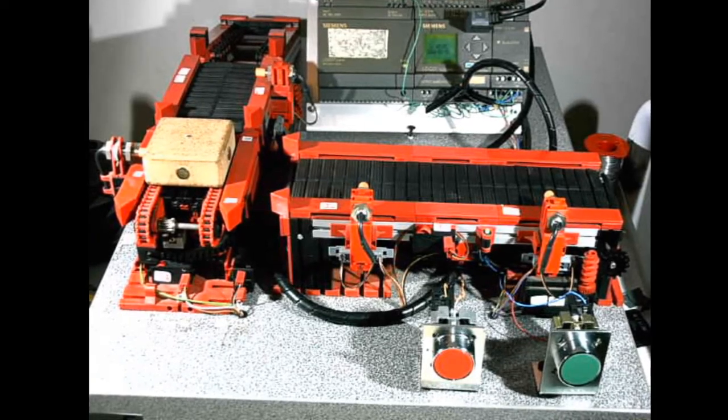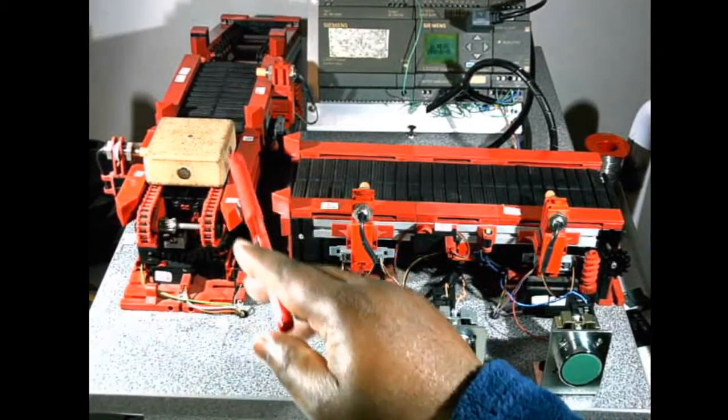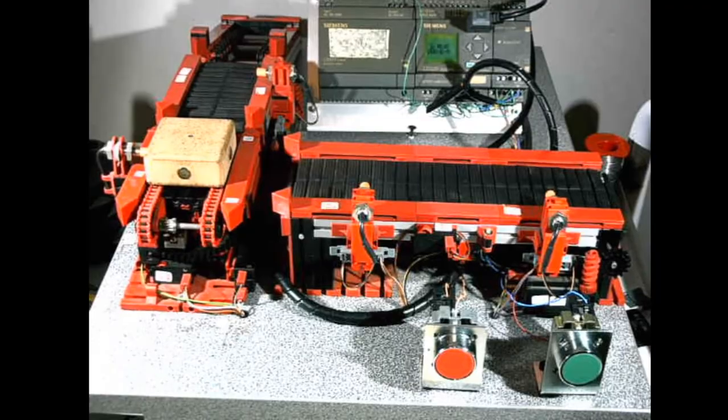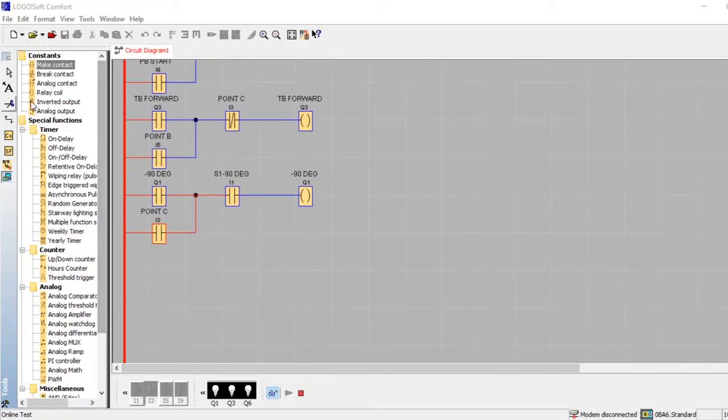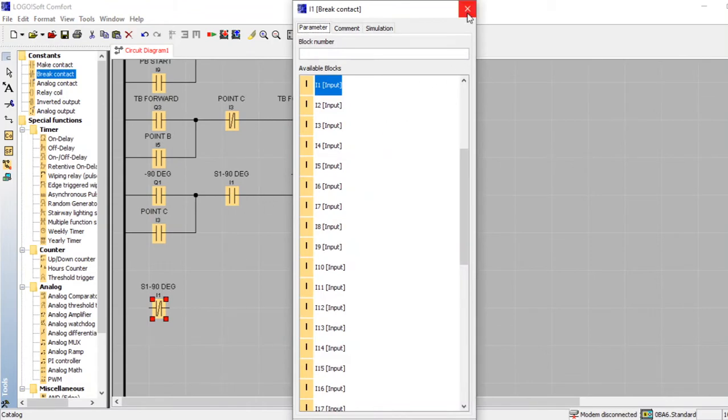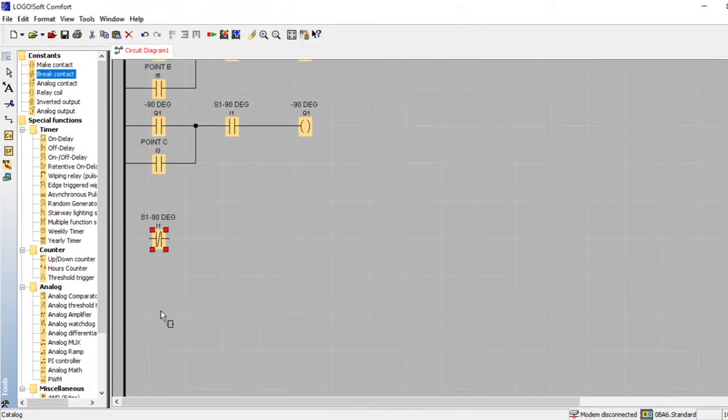It is twisted. Now when I1 is pressed, I'm expecting both this conveyor to go forward, which is Q4, opposite of Q3, and Q7 to be activated. So I1 is pressed. I1 needs to come twice. Here and here. Okay? Activating two things. And one of them is Q4.